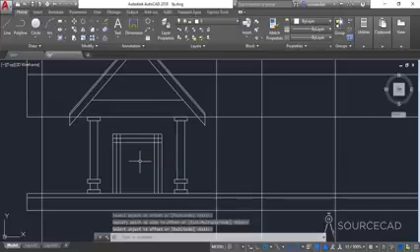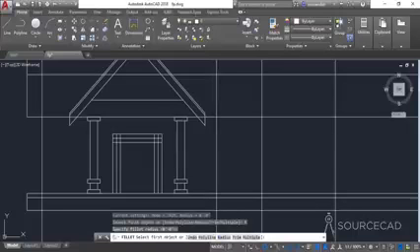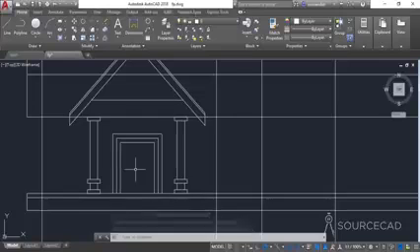All right, now I'll go to fillet, and again I'll make sure radius is 0, press enter, and now I'll actually remove these extra lines here. So I'll click on these 2, and you can see now that this is merging properly. So I'll again do this for this one as well. I'll press enter and I'll repeat the process for these 2 lines and repeat it for these 2 as well. So instead of trimming, I've actually selected fillet tool to make it a lot easier.